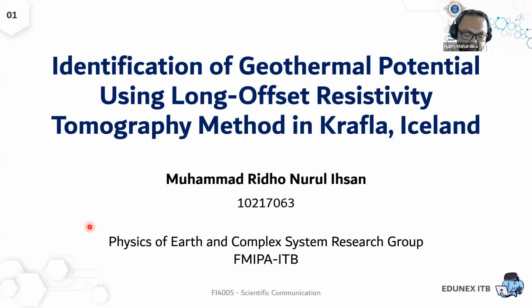The objective of long offset is to get deeper penetration, with the loss of a certain accuracy, because obviously the Wenner has better quality in terms of accuracy, but it lacks when we do some kind of enlargement of the current probe. It will have decreased energy, or current, injected into the ground.